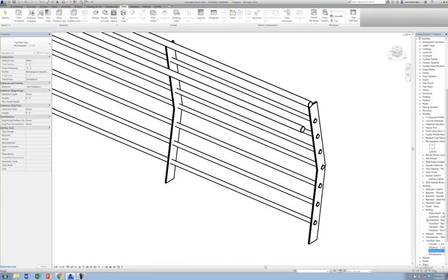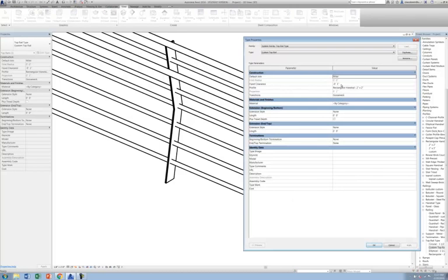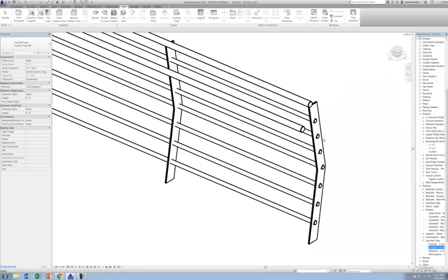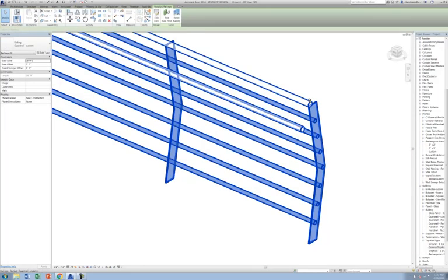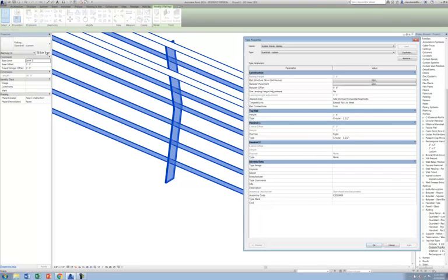So again, I'll right click, duplicate, and right click and rename as custom top rail. And that one we can hit edit type properties, and here we can change the profile for that top rail to the profile that we've made, and then hit OK. Now back in the main family of the railing type, so 3 levels here: railing, then top rail, then profile. We can come in and change the top rail type from circular 1.5 to our custom top rail and hit